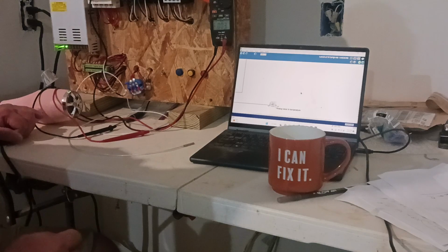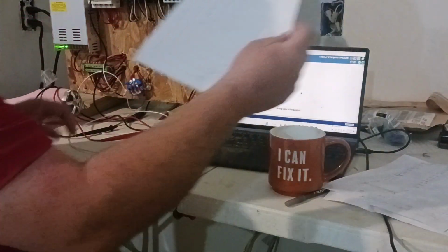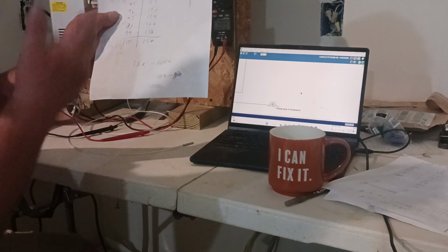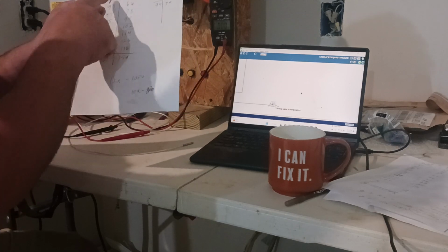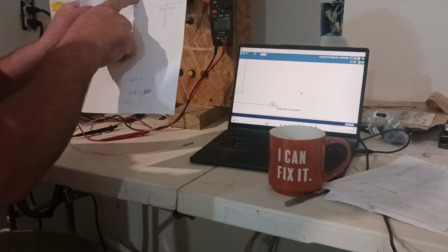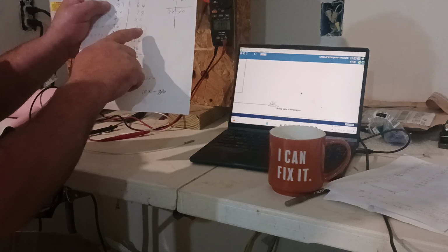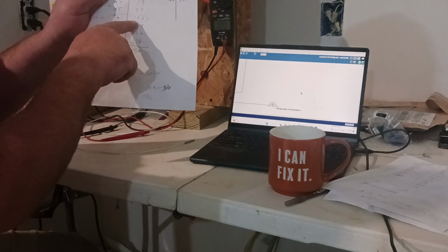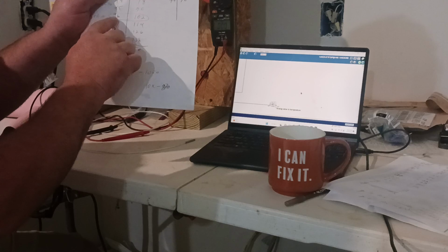Now, how is this scaled? Well, I'll pretty much show you. I don't want to bore you too much with the intricacies of the math, but here's basically the table I came up with. I know this is just kind of chicken scratch to you, but basically, when I had a thermometer and got my temperature sensor down to 42, I was reading 91. And when the thermometer was at a temperature of 102, my value was 96.